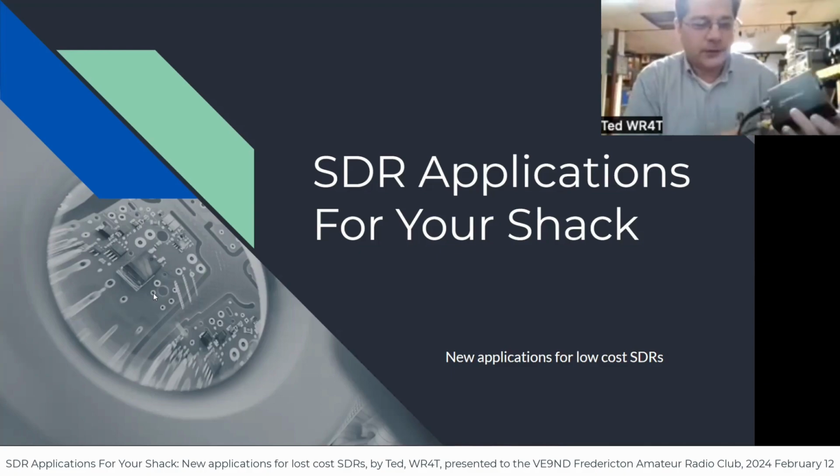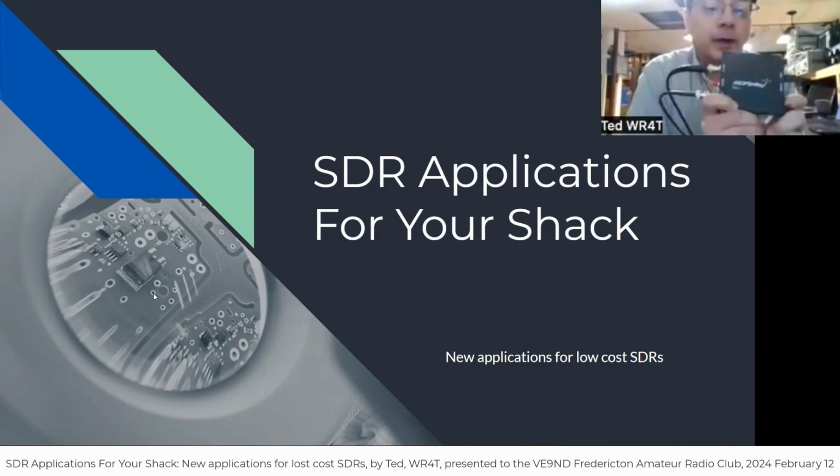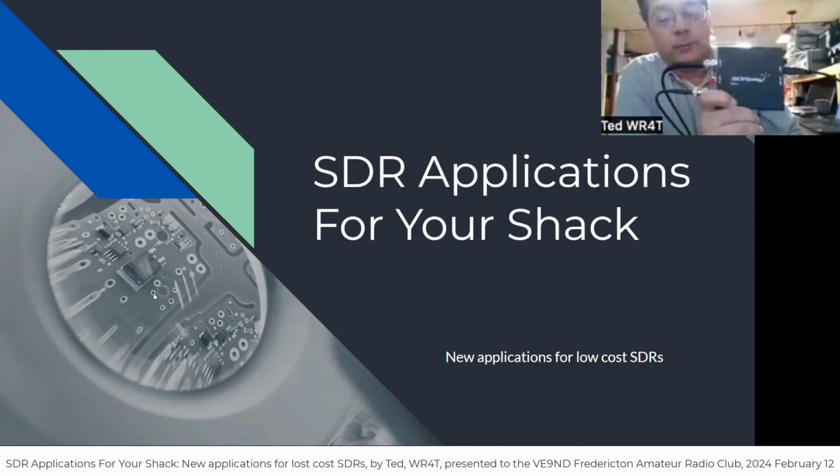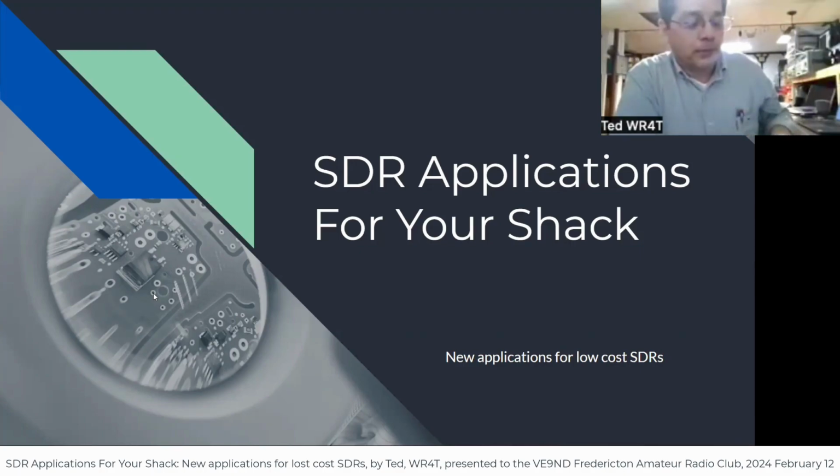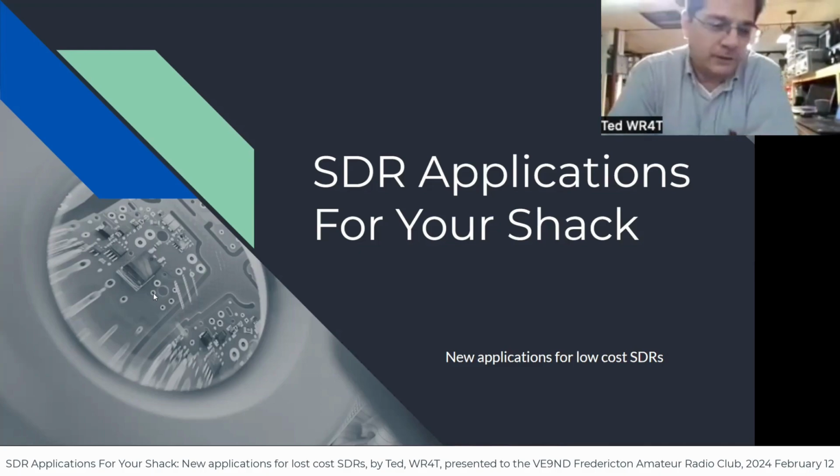First of all, I'm going to hold it up to the camera if you guys can see it. This one is from a company called SDRplay, and there are lots of different companies making these low-cost devices. The thing that I liked about this particular model is that it had very good low-frequency performance, down into the audio range, 1 kilohertz, and my high-end $30,000 spectrum analyzer only goes down to 9 kilohertz. I needed something that did a better job in the audio spectrum.